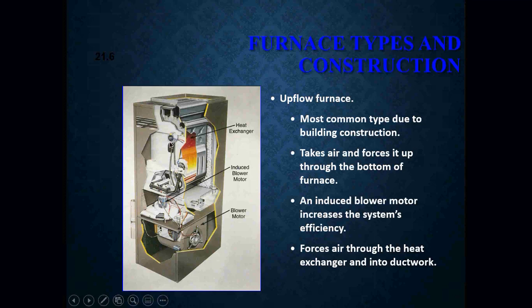So here we are. We have our heat exchanger up here. We have our inducer motor, and we have our blower. So as we are heating the air through our burners, this heat exchanger is going to heat up, get all nice and hot. Our blower is going to turn on, and it's going to force the air up across that heat exchanger and then out into our supply duct into our space.